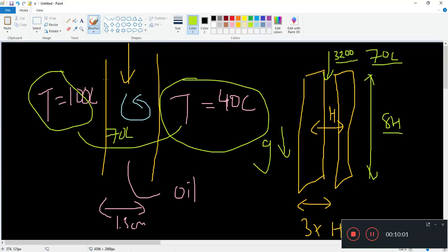So you'll see natural convection that's supposed to go upwards here, and this forced flow is going downwards. Here you will have opposing mixed convection, and here you have aiding mixed convection. So this is sort of the accumulation of everything we have talked about. Sort of a capstone, so to speak, of an experiment that you can just do on your computer, hopefully, if the computer can take it. So we have opposing and aiding flow, and we want to simulate this with DNS as far as we can. And of course, we want to compare how our turbulence models hold up against this quasi-DNS simulation.